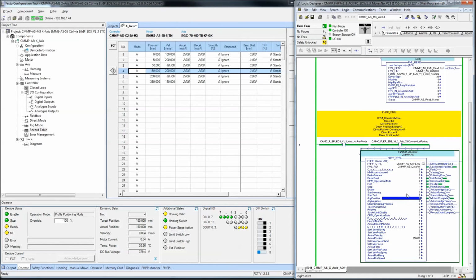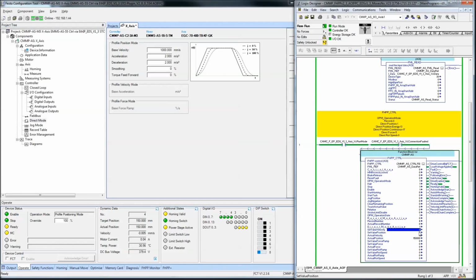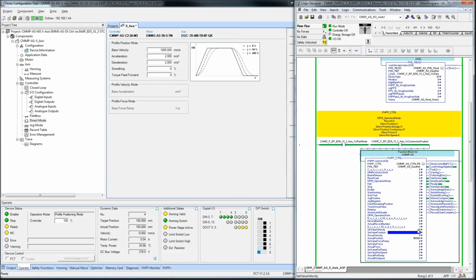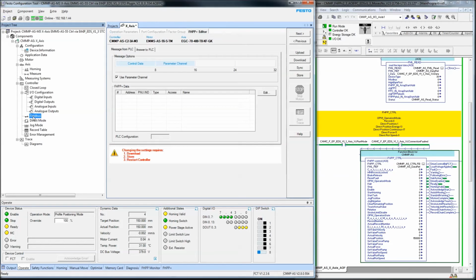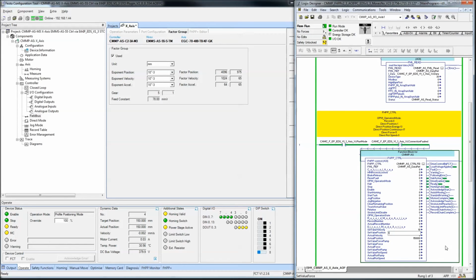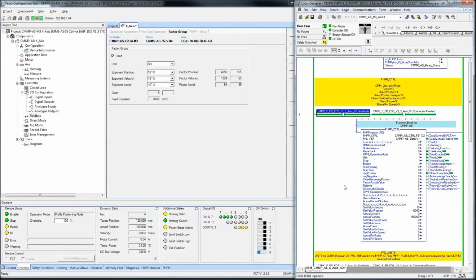Okay, I showed you recently how to do a record. Now if you transition this into 1, it turns it into operation. There's your acknowledgement that you're in that mode. And at this point, you're in direct mode position, and this value, set value velocity, is a percentage of this value here. So I'm going to put in 10%, which should be 100 millimeters. And in the field bus, we have a factor group here. I've got the exponent -3. So if I want the axis to move to 10 millimeters, I would put in 10 and then 3 decimals. Let's see if this gets a little bigger here, maybe it'll be better for you. And again, same idea. This would, of course, be done quicker when you have code, but basically I'm going to put on a start task.